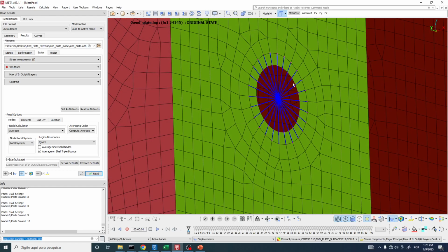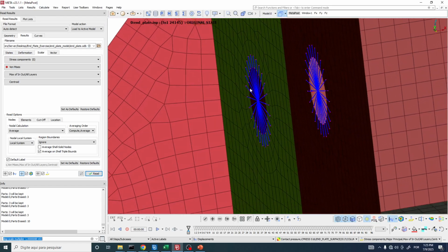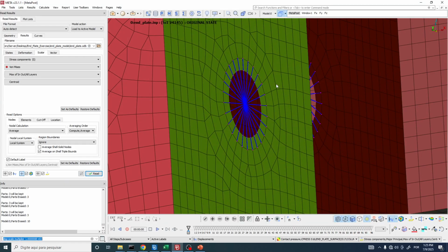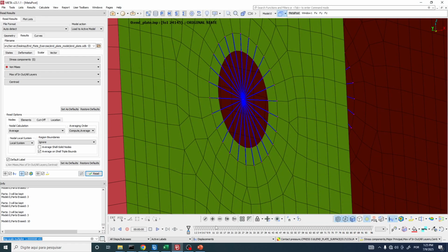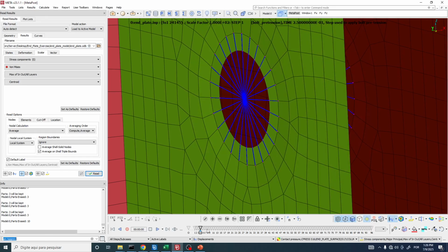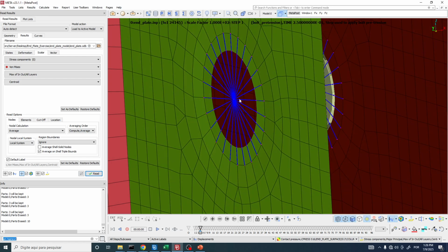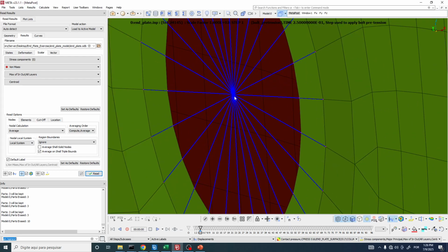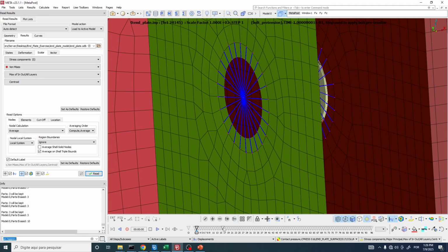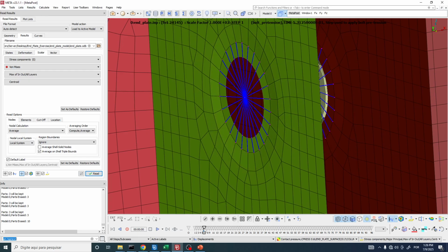Now zoom in here and notice what happens when we have the bolt pretension. When we have this bolt pretension, let me go through the increments. Look at what we have. Since we have put this reference node in the positive x direction, we end up having this force being distributed among the slave nodes of the coupling, and then we end up having this happening.